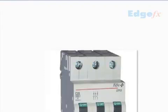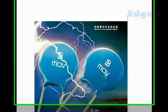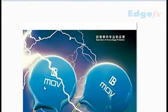AC supply. We have one more protection component, called MOV, metal oxide varistor. These are usually used at the AC input side so that they suppress any extra voltage, because these are normally rated at a particular voltage. After that voltage, this behaves like a short circuit, and in the process it doesn't allow any extra voltage to pass on to the equipment.